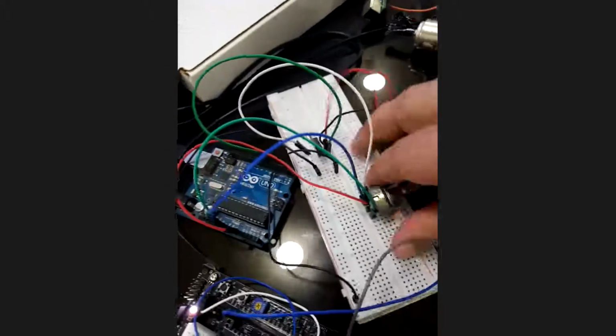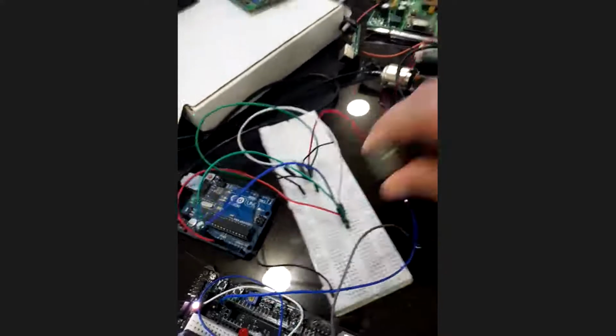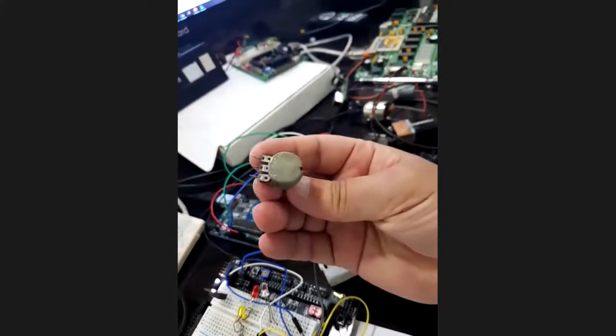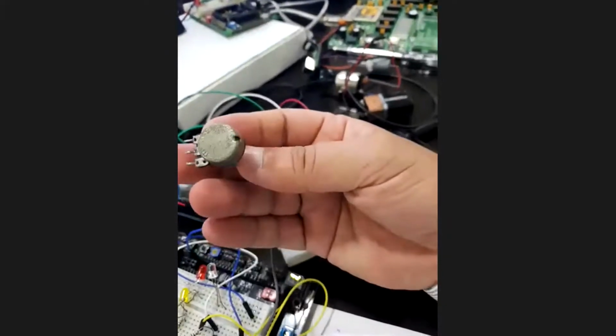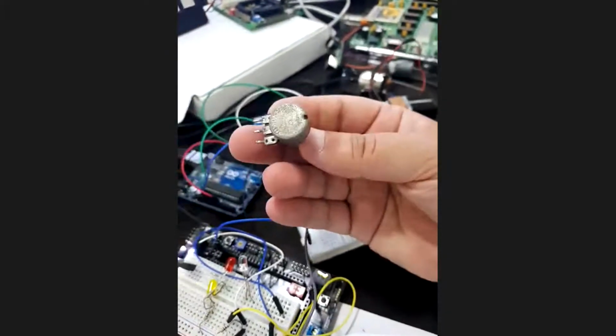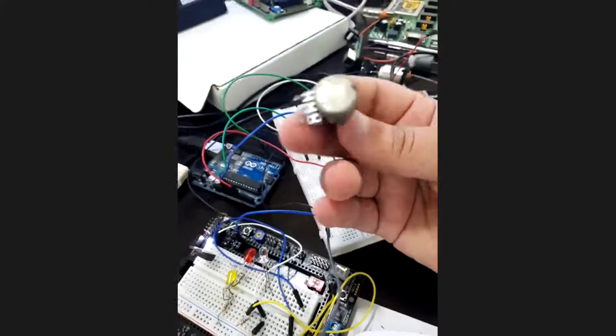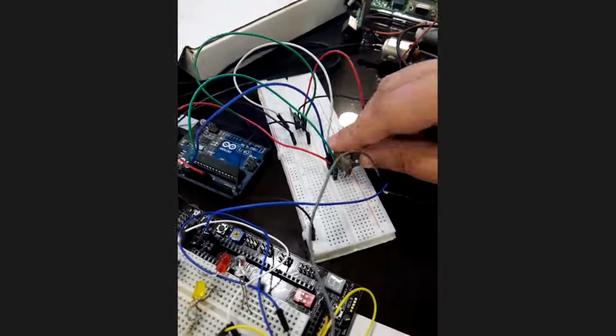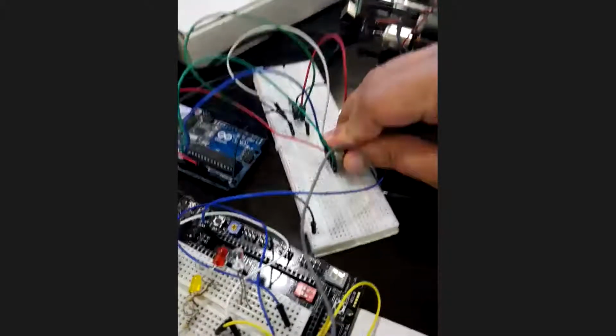How do I connect it? This is it. I connected voltage source to this pin, ground to this pin, and took the middle pin to the analog voltage, to the analog. So I built my circuit here on the breadboard. For the Dragon, it is built for us. This is it.